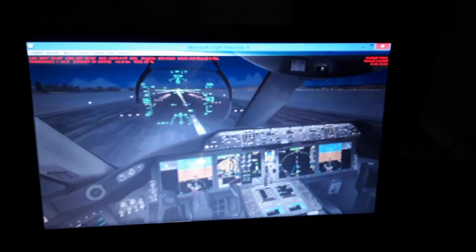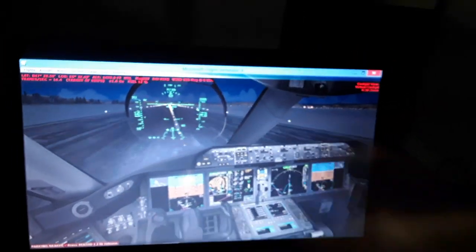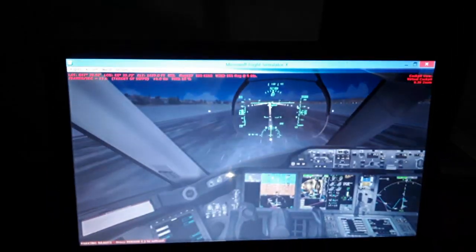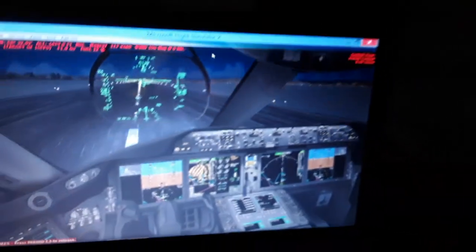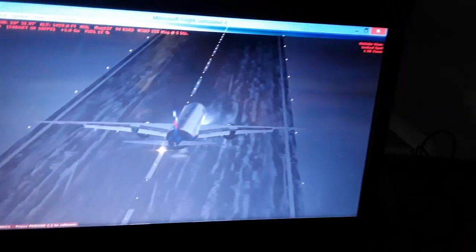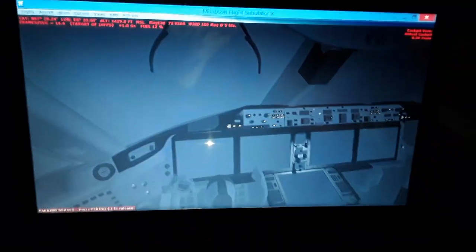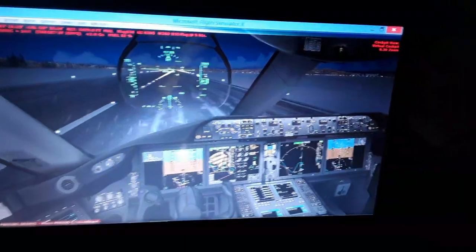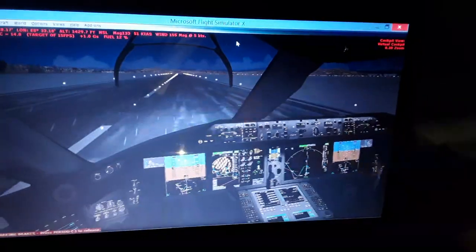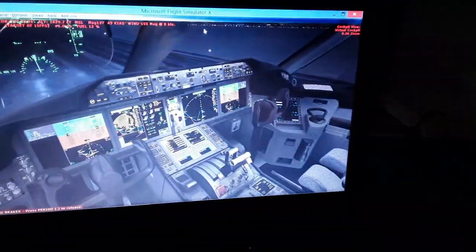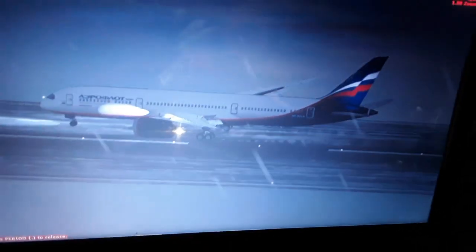Idle thrust, parking brakes, and thrust reverse, full thrust reversers over here, and we maintain the center line for slow down. So you see maintain the center line over here. A little bit left rudder. Also the thrust reverser, we need to align again. So you can see all flight controls, the rudder, and also the nose wheel and the gear behind the nose wheel all